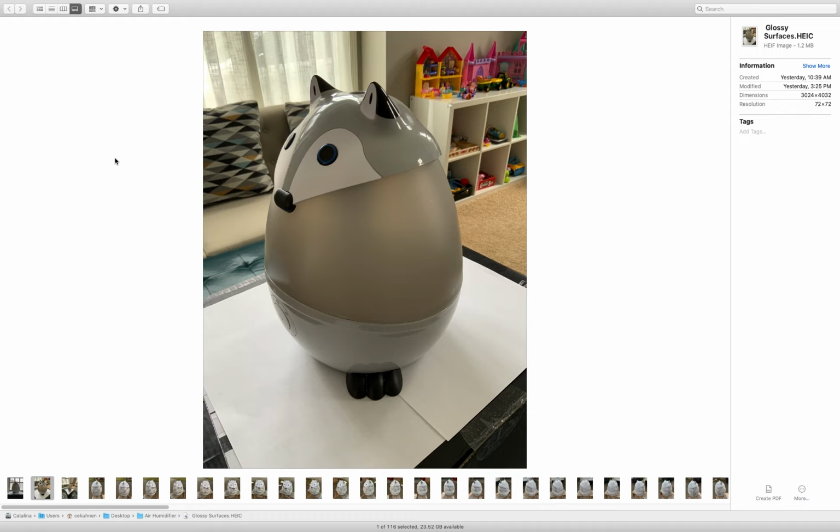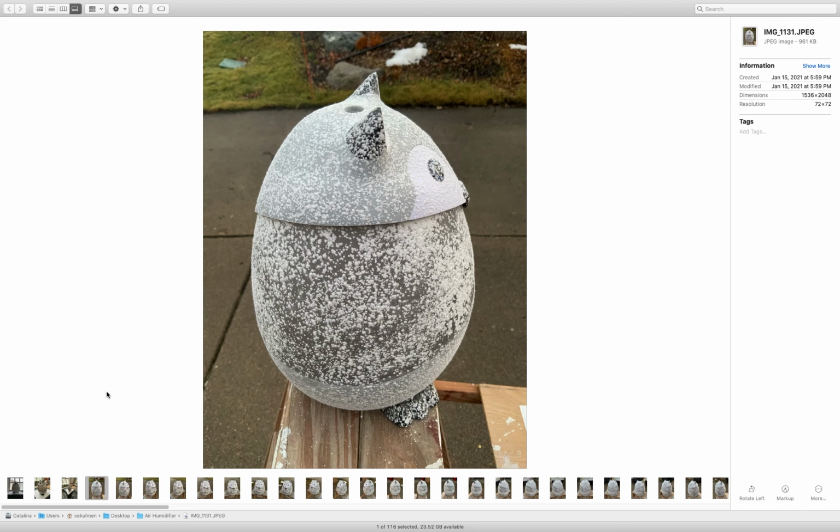That is not very good. And when a surface is too much of the same color, the software really has an issue seeing the 3D dimension of it. So to help this, one very easy way, if you want to do it on a low cost, is simply use cornstarch, which is very thin, and then sprinkle it over the object. You can also use dry hair shampoo spray, which is more expensive, also finer.